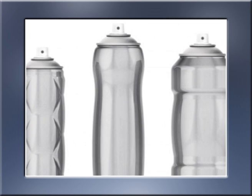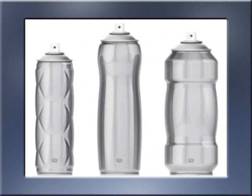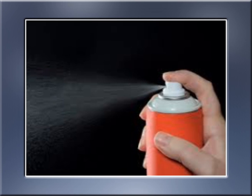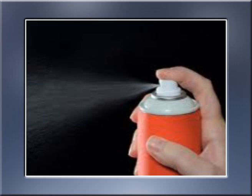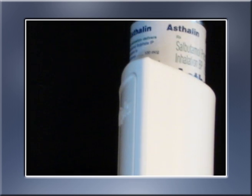Now come to aluminum material. Aluminum is extremely lightweight and is less reactive than other metals. Aluminum containers can be coated with epoxy, vinyl or phenolic resins to decrease the interaction between the aluminum and the formulation. The aluminum can also be anodized to form a stable coating of aluminum oxide.